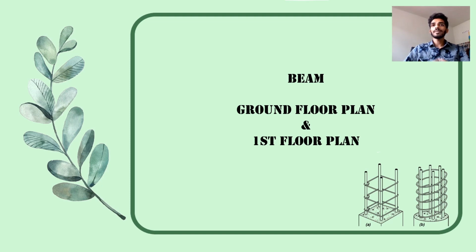So what is a beam? A beam is a structural element that primarily resists loads applied laterally to the beam's axis, as opposed to an element designed to carry primarily axial load, which would be a strut or column. Its mode of deflection is primarily by bending. The loads applied to the beam result in reaction forces at the beam's support points. So this is what we could relate to the beam.